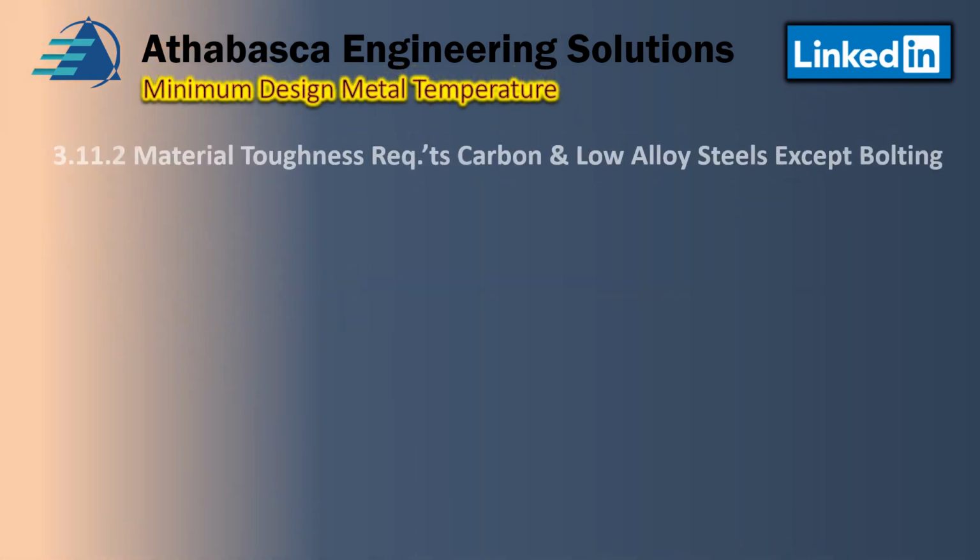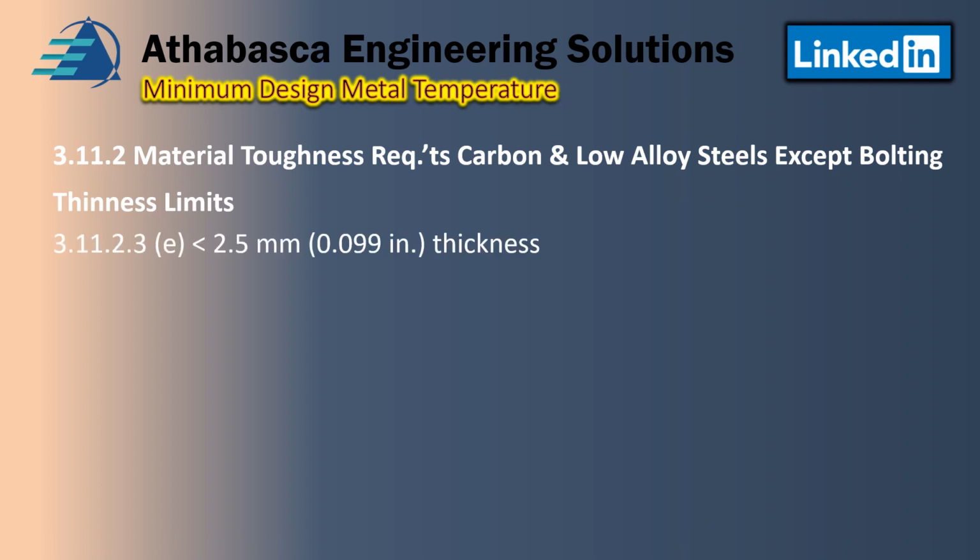We could take a look at the thickness limits, okay? We looked at thickness greater than 1.5 inches, and that's sort of a red flag anyway with Division 1 as well. So whenever you get to that, you should always think about extra requirements like post-weld heat treatment, okay?